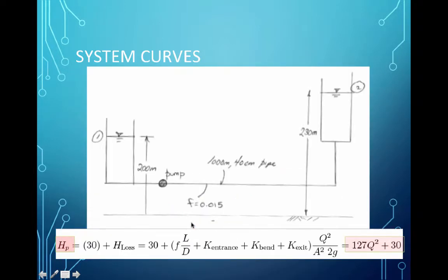So let's consider this system. We'll look at this first as PowerPoint slides, and then we're actually going to extract these out as an actual hydraulic system. We'll use our online toolkit to construct some performance values of how this system would operate, and that will let us generate a system curve, and then we can go look at some pump curves to satisfy it.